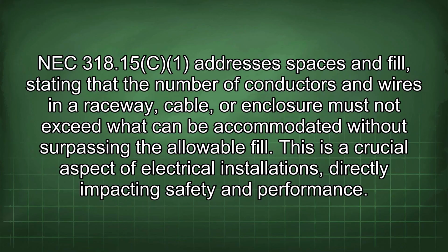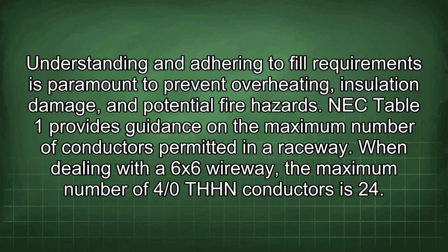NEC 318.15 addresses spaces and fill, stating that the number of conductors and wires in a raceway, cable, or enclosure must not exceed what can be accommodated without surpassing the allowable fill. This is a crucial aspect of electrical installations, directly impacting safety and performance. Understanding and adhering to fill requirements is paramount to prevent overheating, insulation damage, and potential fire hazards.